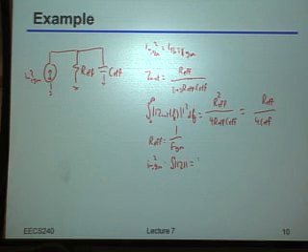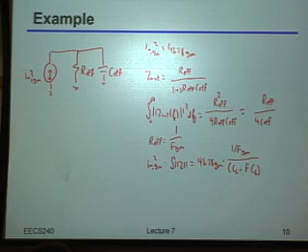That's just going to be 4 kT gamma GM times 1 over F GM divided by 4 times CL plus F times CS. Does this make sense to everybody? Now, nicely enough, the GMs are going to cancel each other out. Oh, I'm sorry, I missed a 4 on the bottom down there. The 4s are going to cancel each other out.